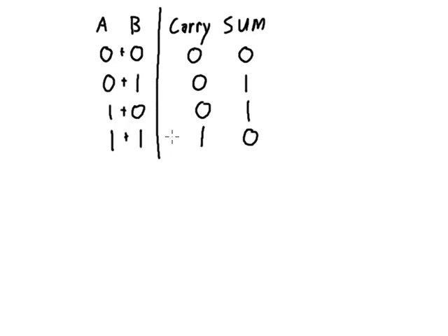But if we treat this as a truth table where we have two inputs creating two different outputs, we can figure out what carry is as a function of A and B and what sum is as a function of A and B. Let's delete these addition signs.